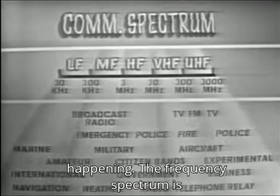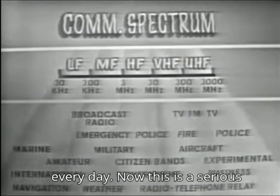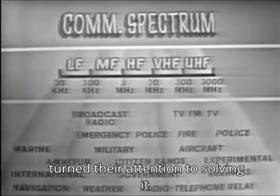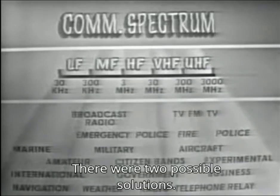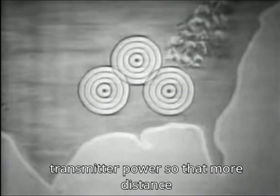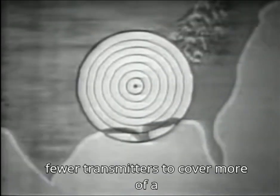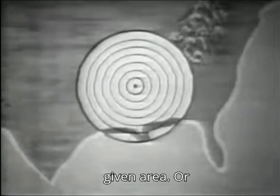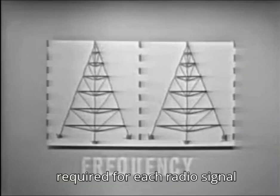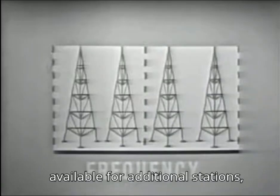And you can see what's happening. The frequency spectrum is already too crowded, and getting more so every day. Now, this is a serious problem. So electronic engineers turned their attention to solving it. There were two possible solutions. One, to increase the efficient use of transmitter power so that more distance could be obtained, which would enable fewer transmitters to cover more of a given area. Or two, to narrow the frequency bandwidth required for each radio signal, so that more frequency space would be available for additional stations.